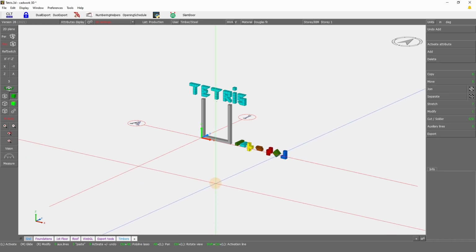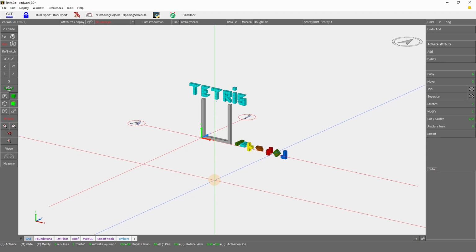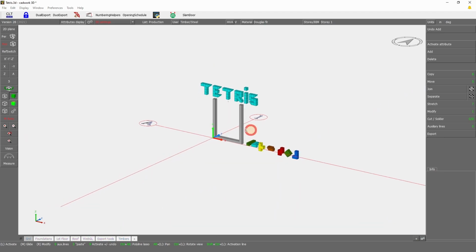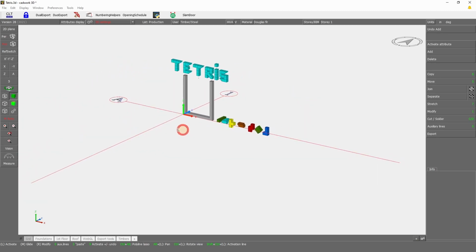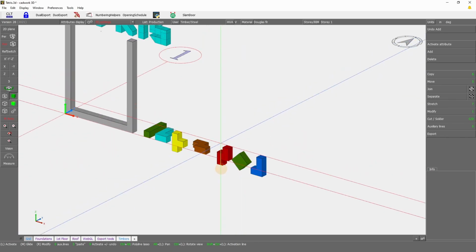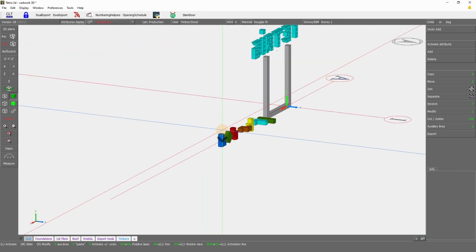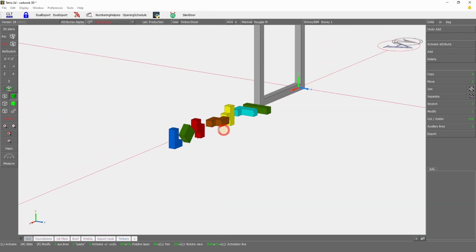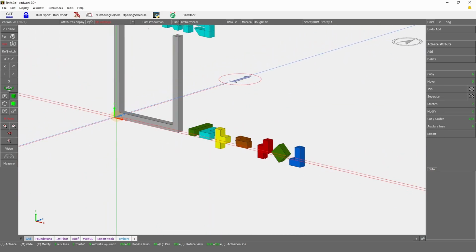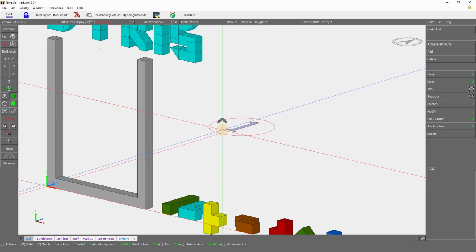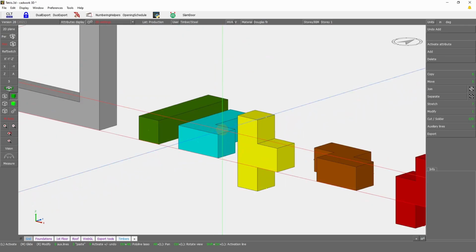The same goes for the pan, so it's simply, instead of Control, it's Alt with the left click, and then you release Alt, and then you can just pan around. So this is how you navigate through your model and look around. Always recall that when you zoom in, you zoom toward your cursor location.